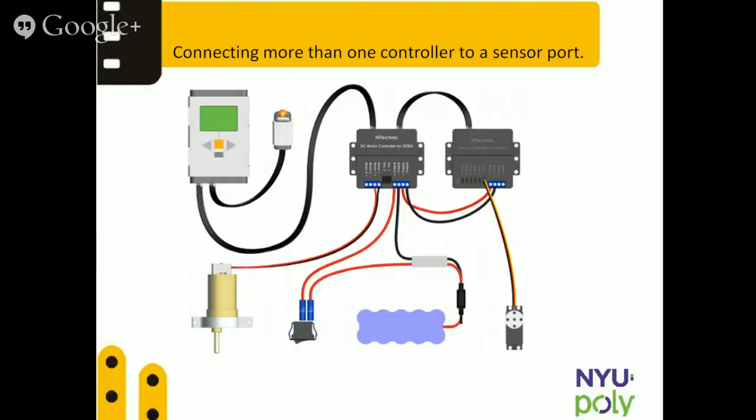We can also see that there are black wires being connected to the brick. These are necessary because ultimately we are going to give the output from the brick, and the brick has to be controlling those servo controllers or DC motor controllers. On the second controller we can see that there is a servo connected to it. This servo is the motor that we were talking about, which can rotate from 0 to 180 degrees, and every degree can be controlled via our RobotC program.